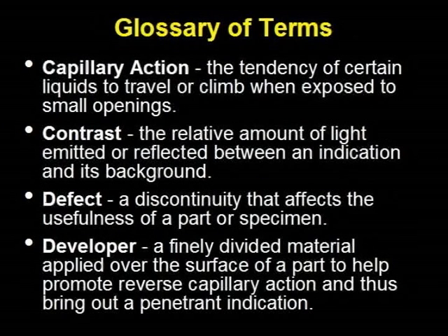The following glossary of terms defines some of the terms used in penetrant testing. Capillary action is the tendency of liquids to travel or climb when exposed to small openings. Contrast is the relative amount of light emitted or reflected between an indication and its background. A defect is a discontinuity that affects the usefulness of a part or specimen. A developer is a finely divided material applied over the surface of a part to help promote reverse capillary action and thus bring out a penetrant indication.